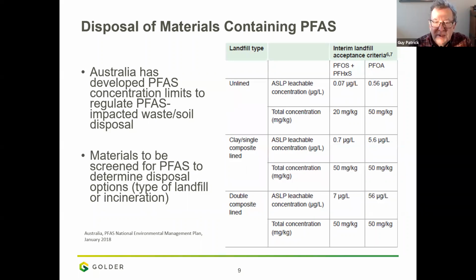Hey Ryan, is it fair to say that that Australian leach procedure is analogous to the TCLP? It's a similar procedure. There are some differences, as I understand, but yes, on the whole, I believe you can use the SPLP or the TCLP, which would be used in the U.S. The pH is a little bit different, but yeah, very similar procedures.